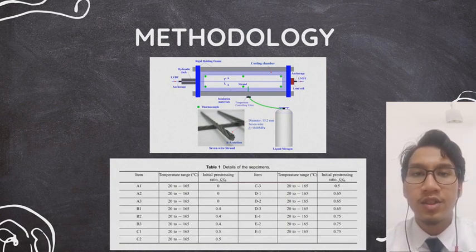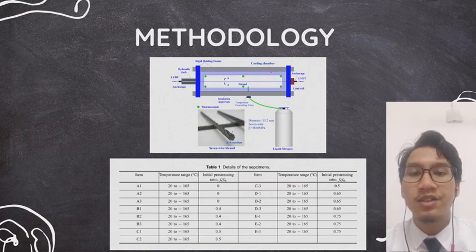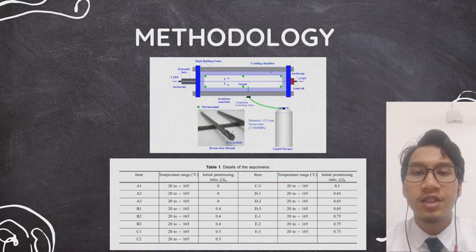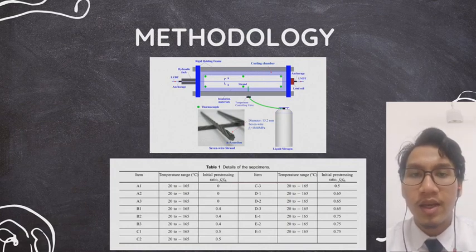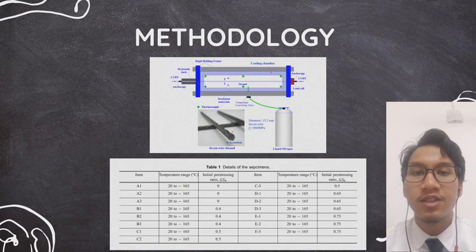After that, the temperature in the cooling chamber was gradually increased to the ambient temperature step by step. During this heating process, linear variable displacement transducers, LVDT, were used to monitor the displacement at the two ends of the steel strand as shown in Figure 1. All the readings of the sensors, including the thermocouples, load cell, and LVDT, were monitored and recorded by software running on the PC during the testing. And each group contains 3 identical specimens.